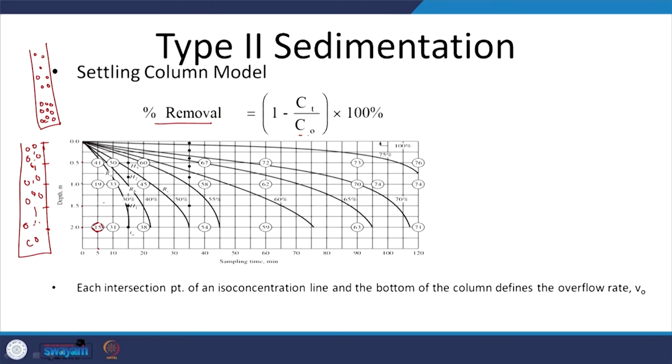So, that is what I am trying to point out by drawing a relatively poor figure. We will see relatively greater removals even at shorter time periods at the shallower depths, but not as much removal at the deeper depths. Obviously, with increasing time at the same depth, the measured values given in the circles are going to increase, and again with depth the percentage removal will decrease.